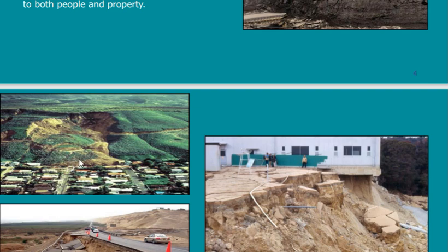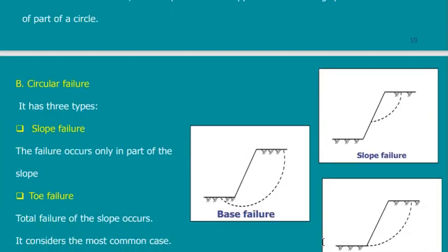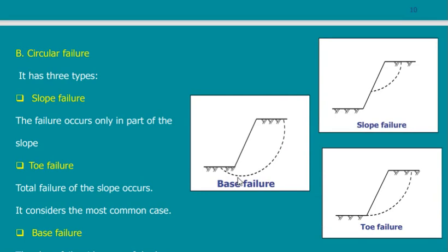It may be a toe failure, and it may be a base failure, but the photo is not clear, because I cannot really judge from this location where the end of the failure is. But it seems to me that it is more or less like this case, which is a base failure, because I see some soil gathered on top.